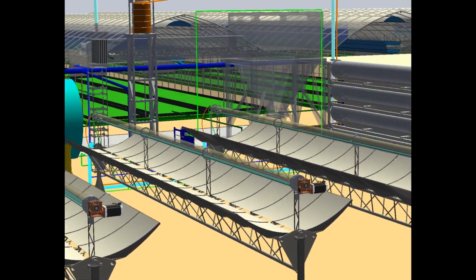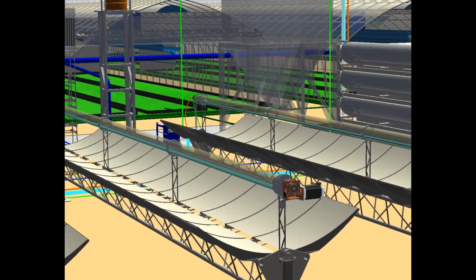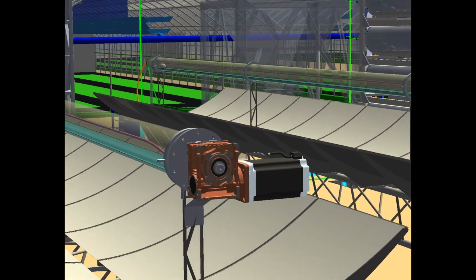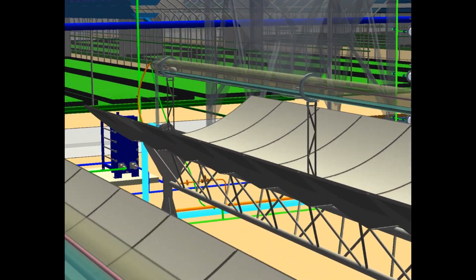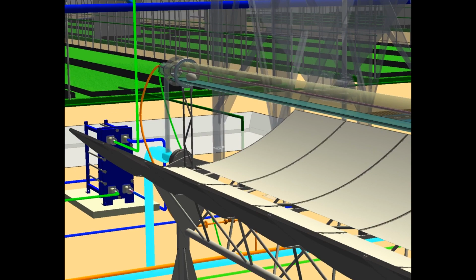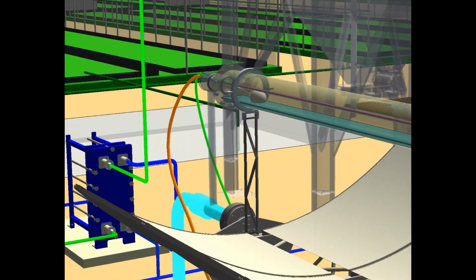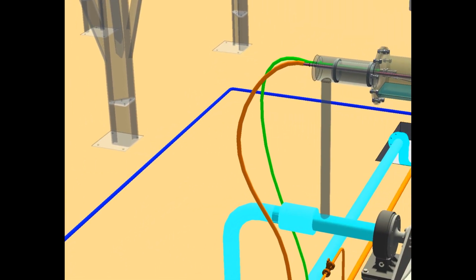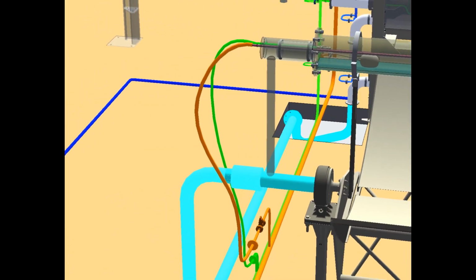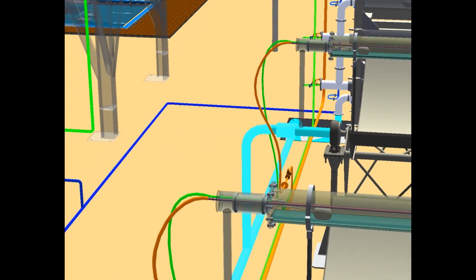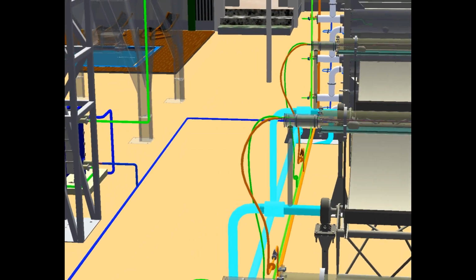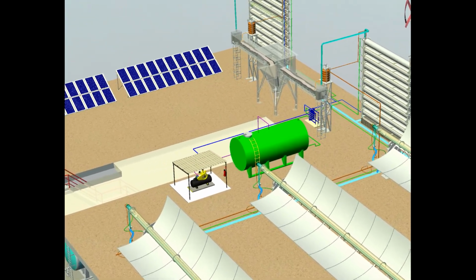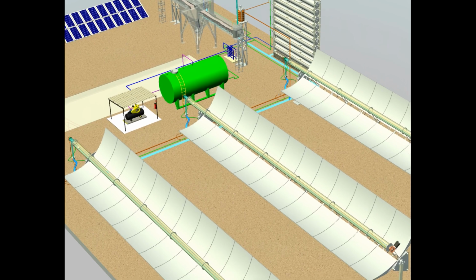Heating of film evaporation drums can be done in different ways. In a solar desalination plant, steam is generated by solar energy, which is concentrated in a parabolic reflector. The internal structure of a rotating drum installed in a parabolic reflector with a single axis of rotation is similar to that already discussed for the evaporator module. Similar reflectors are used in solar power plants to heat circulating molten salt. The outer surface of the rotating drum installed in the reflector should be covered with a light-absorbing coating to increase the efficiency of solar energy use.